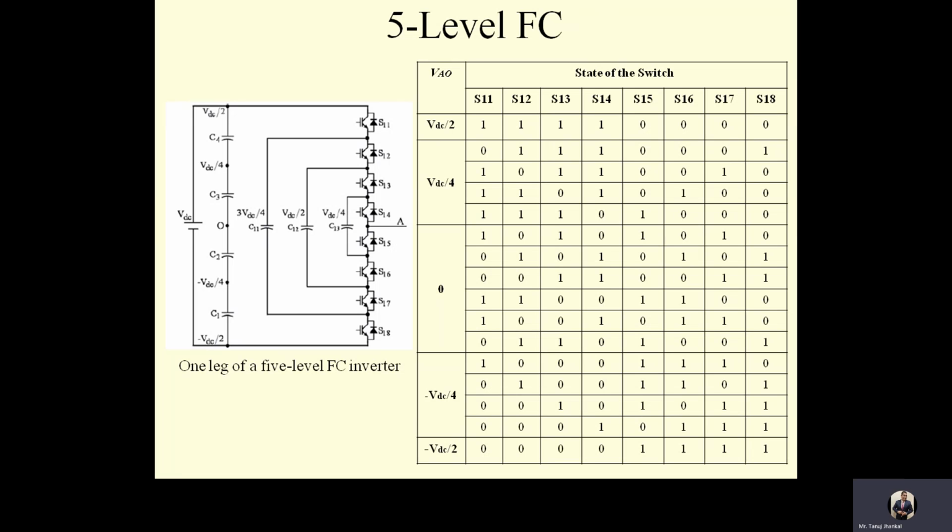Now coming to another topology of multi-level inverter, which is the Cascaded H-bridge. The multi-level inverter structure can be realized by cascading or connecting in series several single-phase H-bridge structures with separate DC sources, and this technique has been adopted for high power induction motor drive applications.